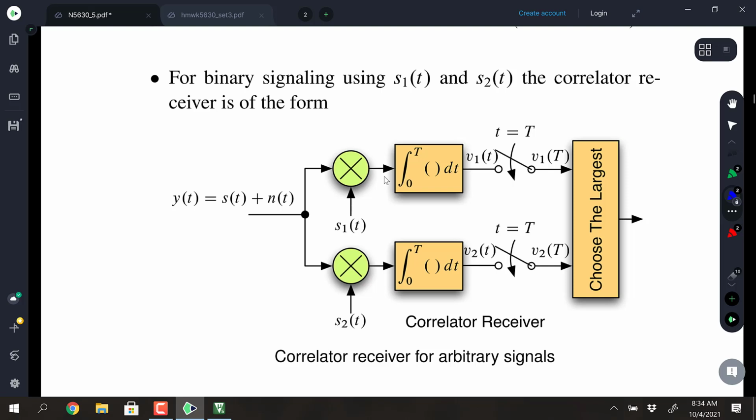So the CFAR idea is where you hold fast to the idea that you want to ensure no false alarms. And in a simple radar application, a false alarm occurs when noise gets confused with signal. It's just noise present, don't get excited. Because if you keep lowering your threshold down to the noise floor just to make sure you can detect a really weak signal, you're going to increase the chance that you falsely declare noise as being signal. So that's where that idea comes from.